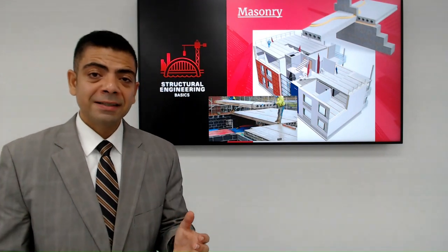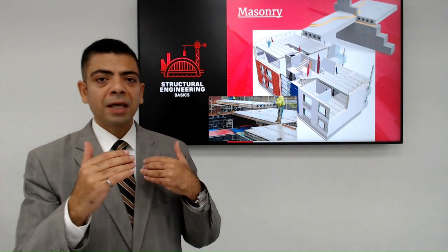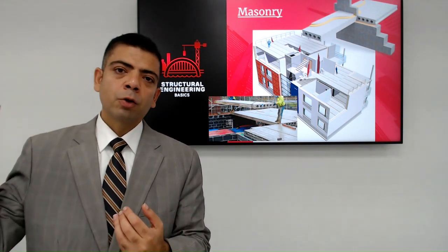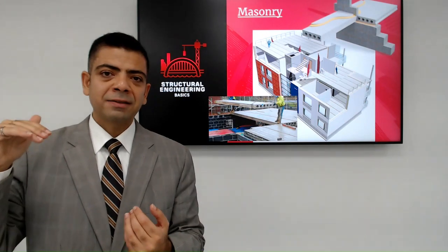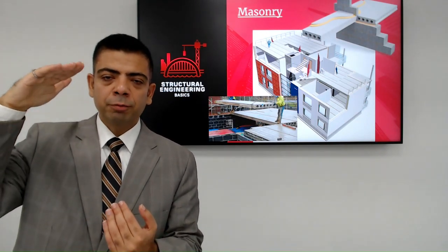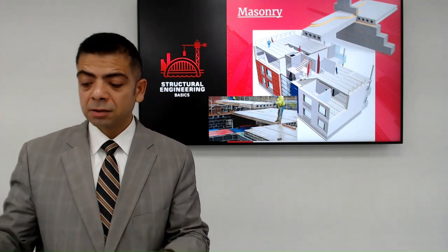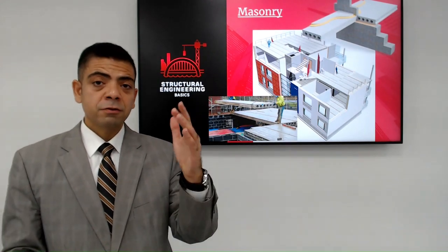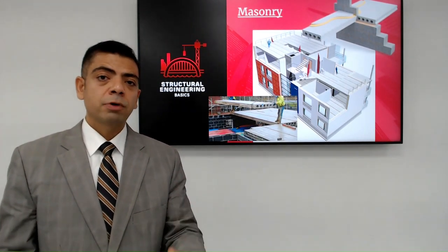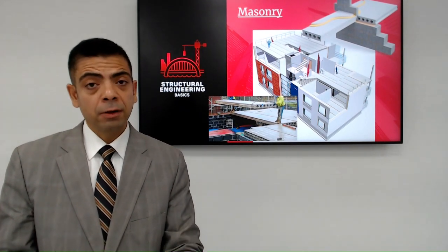A very common system, I see it a lot, combines the relative ease of masonry walls with the quick and fast precast hollow core systems. So it's slabs made out of precast hollow core on top of masonry walls. The multi-story building can go relatively high, not as high as reinforced concrete with high strength, and relatively quickly.